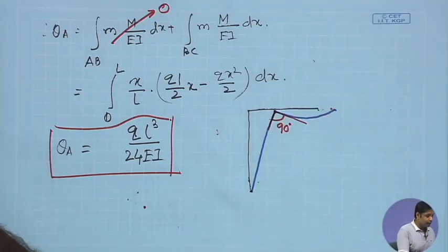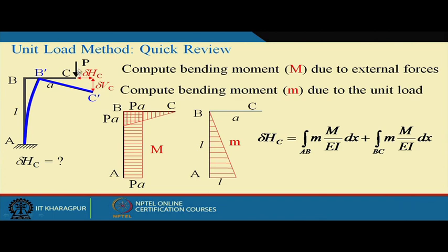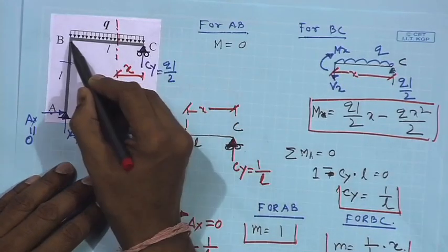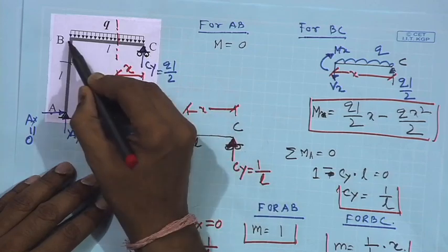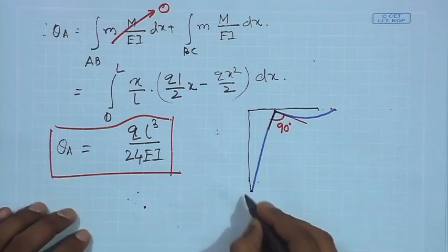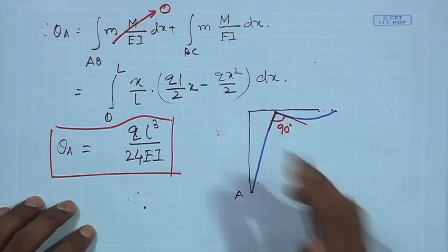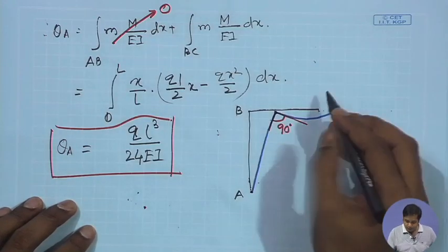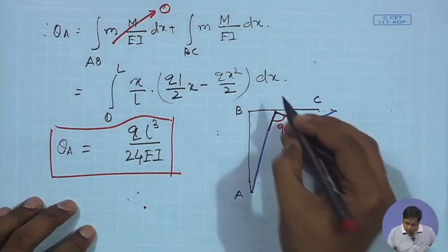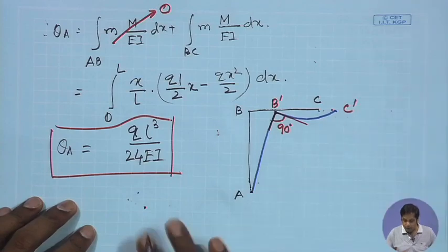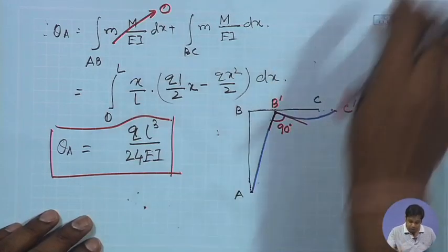But if you look at a similar problem where the load is a concentrated load, this was the deflected shape. So, this is almost a straight line. It is not sagging like this. But in this case it will sag because this beam BC is supported at C and supported at B, and it is subjected to a uniformly distributed load. So, this could be the probable deflected shape. I am saying probable because you need to find out the actual deflected shape. Based on the information that we have, we can say that could be the deflected shape of this structure, but that you have to verify.